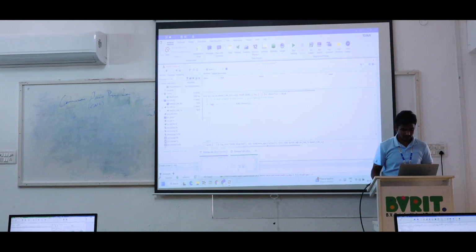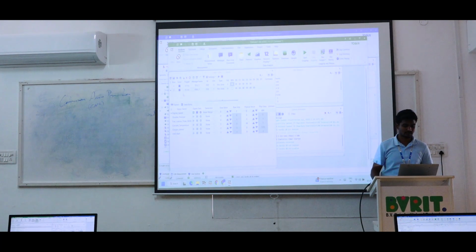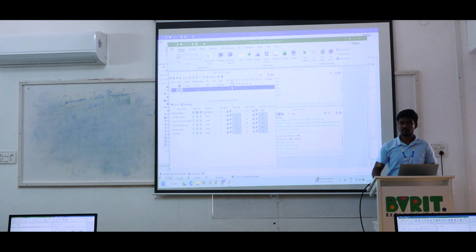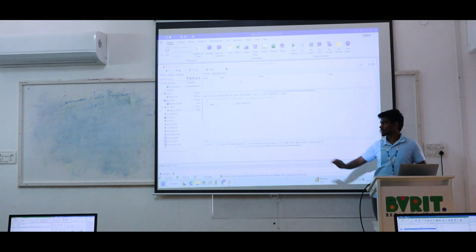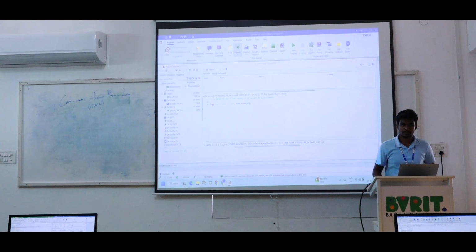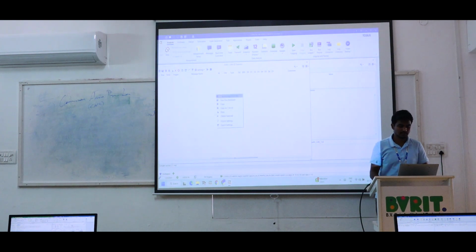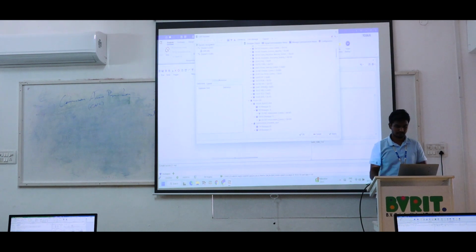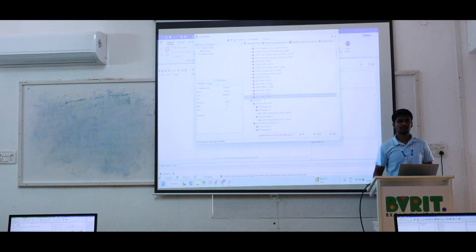So just stop it here, which means in the new window, you just stop the EMS message. Just stop the EMS only, not ECM, EMS alone. Okay? Stop it, minimize the tab and go to this CAPL scripting tab. Open the transmit window. From the CAPL scripting tab, open the transmit window. So it is an empty transmit. Here you just add the message of EMS.